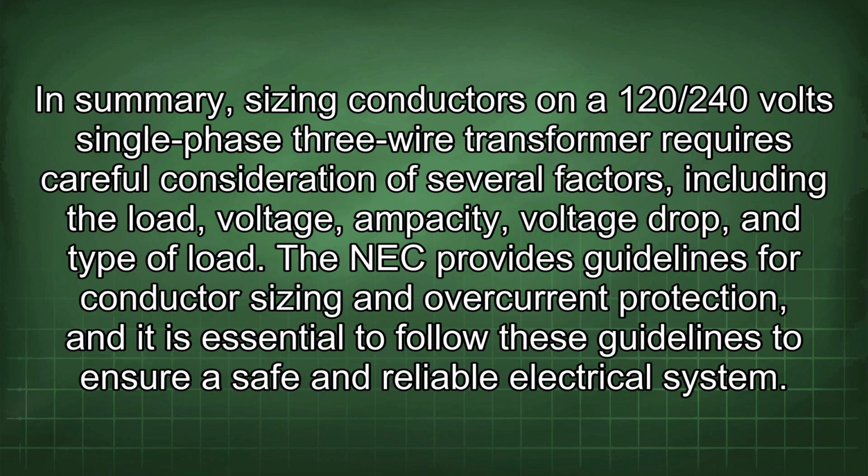In summary, sizing conductors on a 120/240 volt single-phase 3-wire transformer requires careful consideration of several factors, including the load, voltage, ampacity, voltage drop, and type of load. The NEC provides guidelines for conductor sizing and overcurrent protection, and it is essential to follow these guidelines to ensure a safe and reliable electrical system.